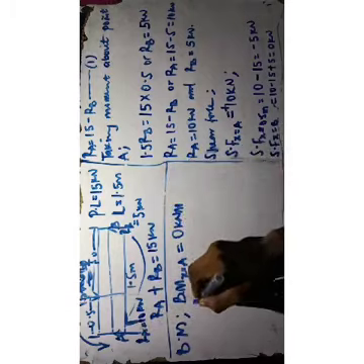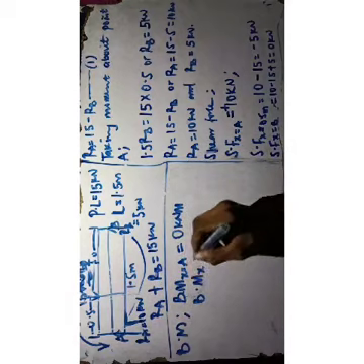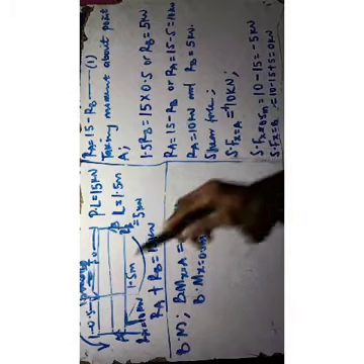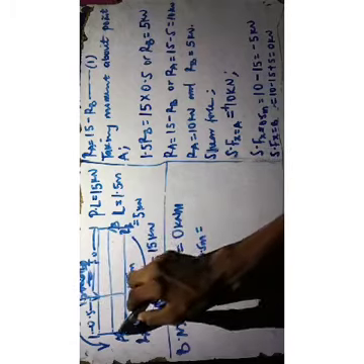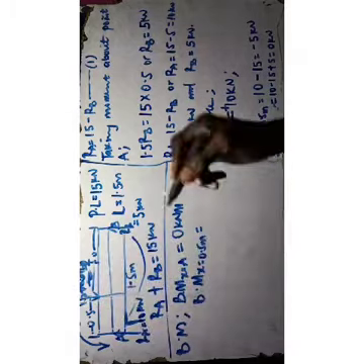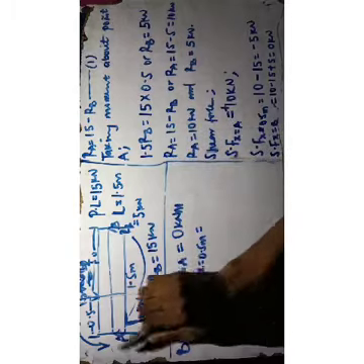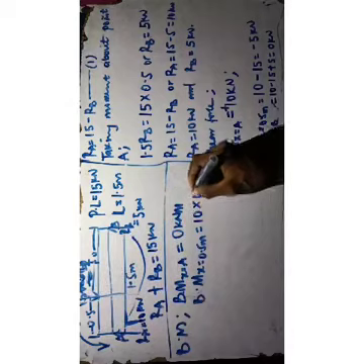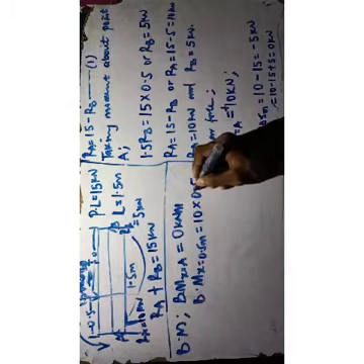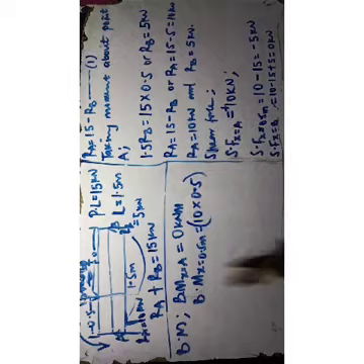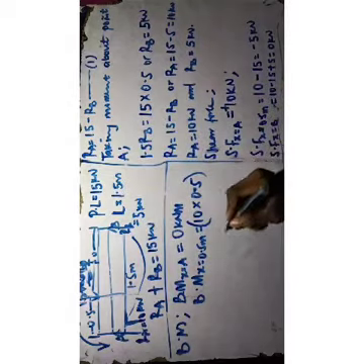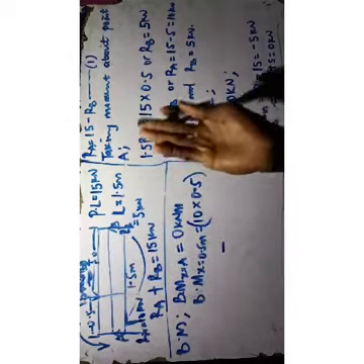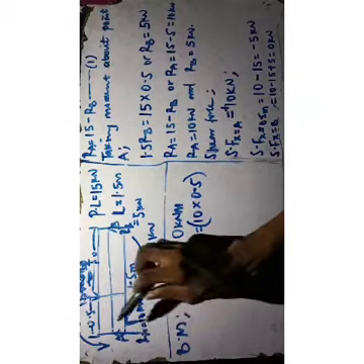And the bending moment at x equal to 0.5 meter, at this point you take clockwise. For clockwise, RA is covering 0.5, right? That will be 10 times 0.5 clockwise minus anticlockwise, minus 15 times 0, right? So that will be 10 times 0.5.